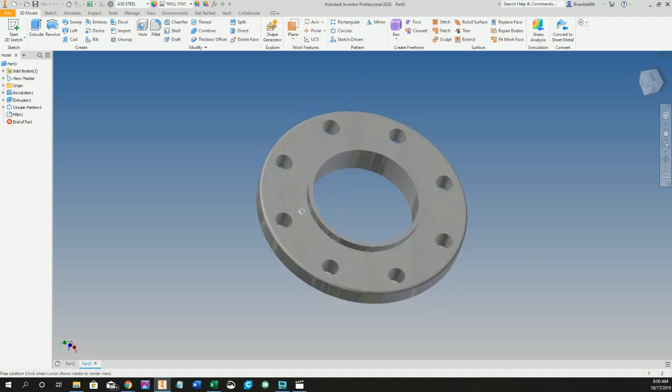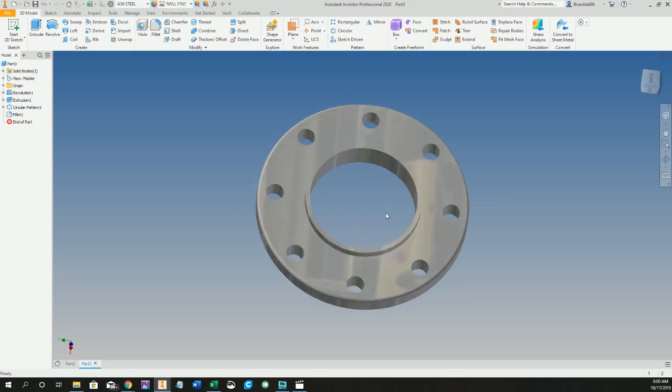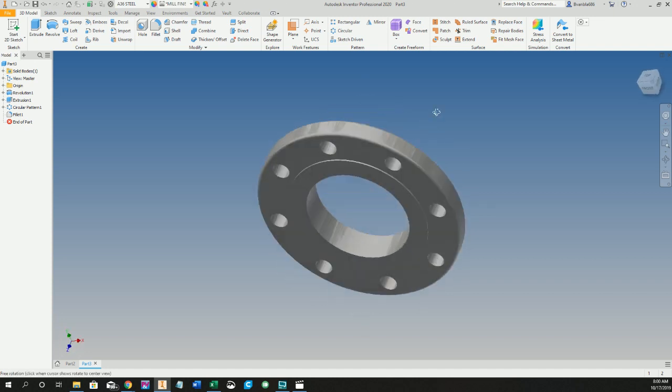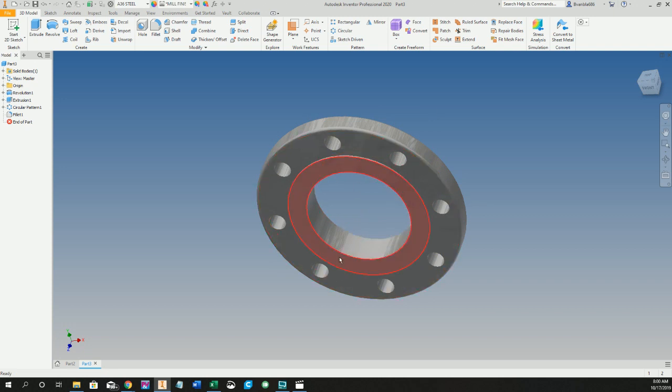Those are super useful, especially when you've got your own part numbering system. The library parts in Inventor, it's a little bit more tricky to change the part numbers and the descriptions, and a little bit more difficult to understand their way of picking the different sizes. So I like to use iParts, and we can cover that a little bit later.